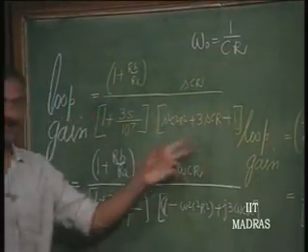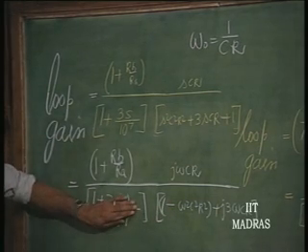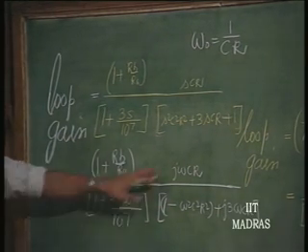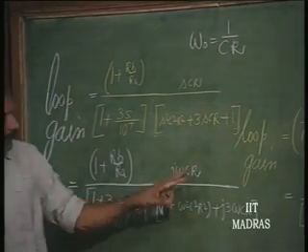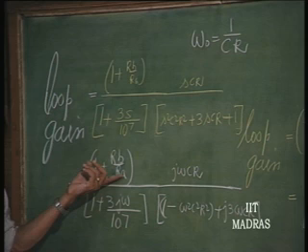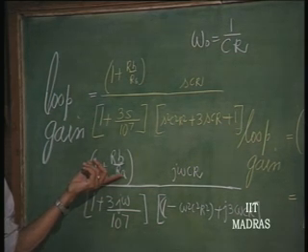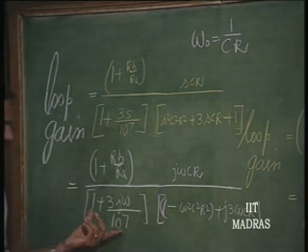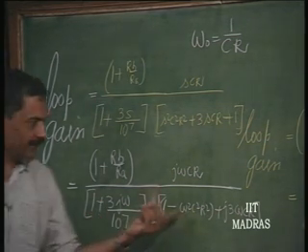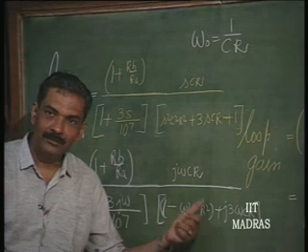The phase shift of this becomes equal to 0, and this, if it is ideal, is not contributing to any phase. So, this particular thing has a magnitude then of 1 over 3, which has to be made equal to 1 by making this equal to 3. That is what we got as condition for oscillation. Now, because of the additional phase shift here, phase lag here, this phase shift cannot be equal to 0.